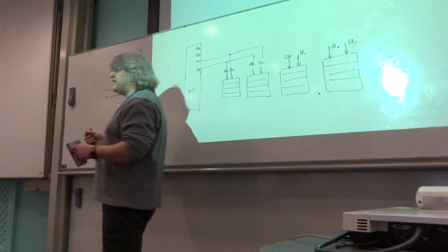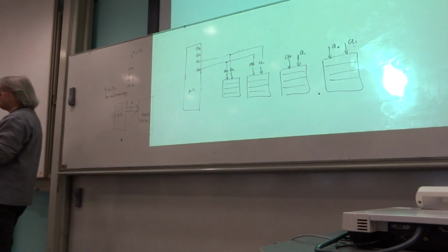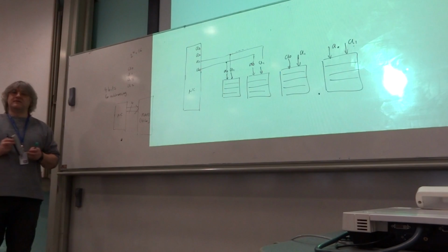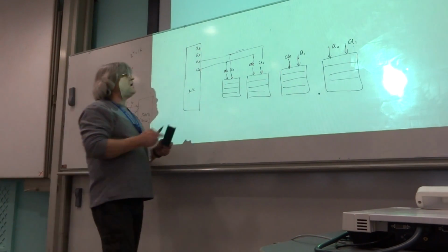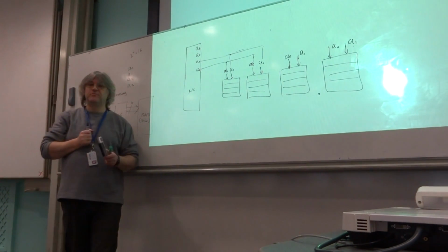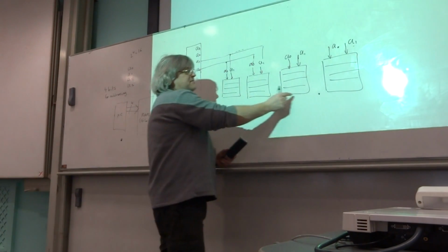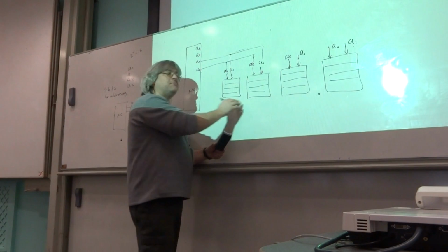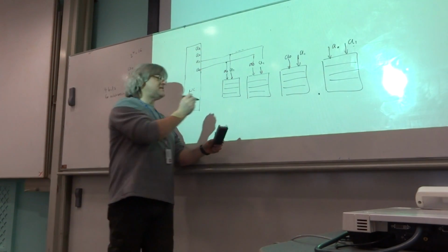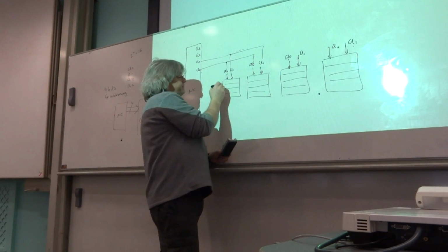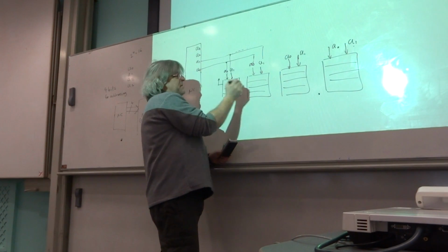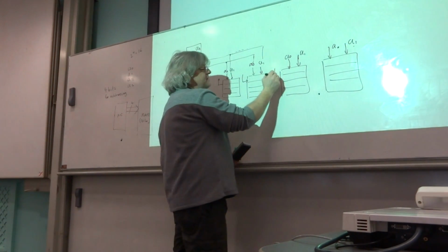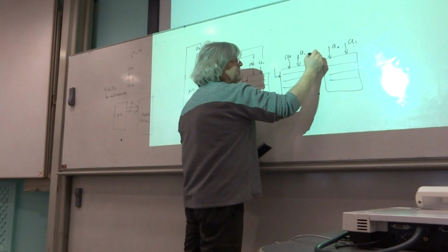We've got to engineer things so that at most only one of them is ever active. Okay? Now we do have some additional address lines here. The problem is each of these devices doesn't have any more address lines. But what you tend to find is manufacturers of these devices provide you with a special signal, a special pin, which is called chip enable.